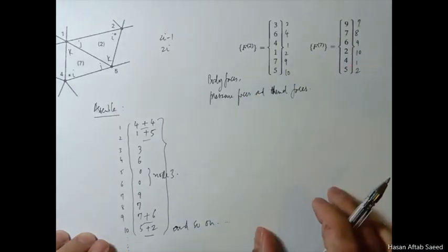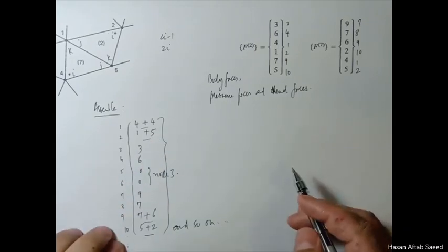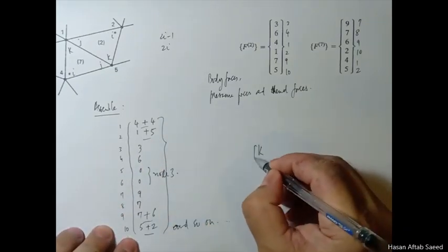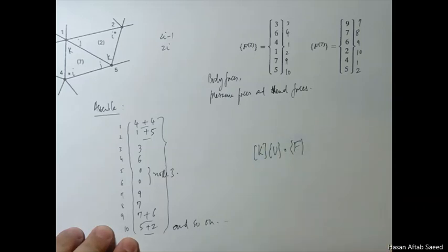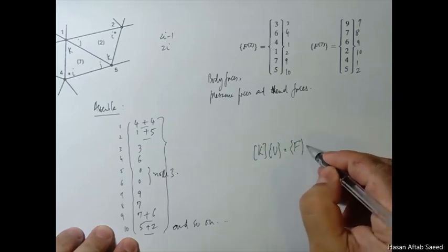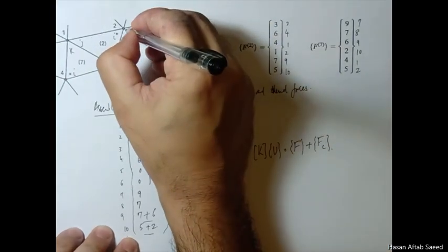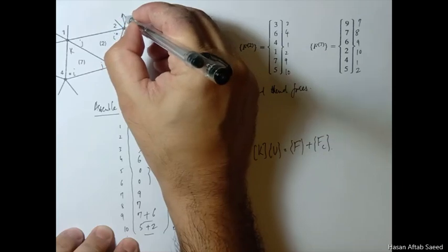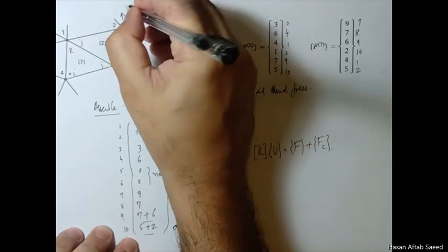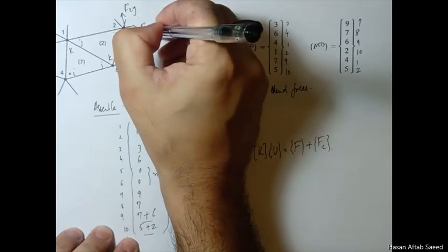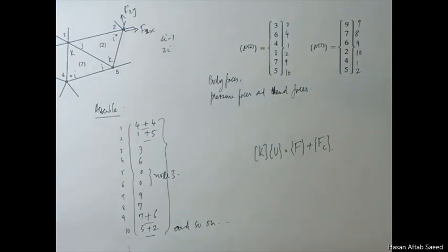We have just shown 2 elements. When you have assembled all the elements, then you have this F matrix, and as a result, Ku is equal to F. At the very end, we just add the concentrated load vector. For example, here there's a load F2x, F2y.